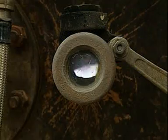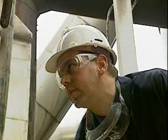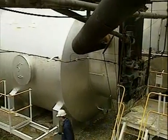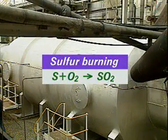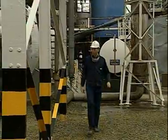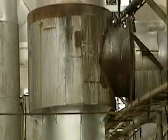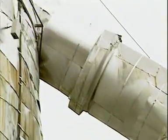The sulphur is sprayed into a furnace where it burns in the dry air. Sulphur combines with oxygen in the air to form sulphur dioxide. The oxidation produces large amounts of heat. That heat is used to boil water to produce steam to generate electricity. The gas mixture, which leaves the furnace, contains sulphur dioxide and enough oxygen for the next stage.